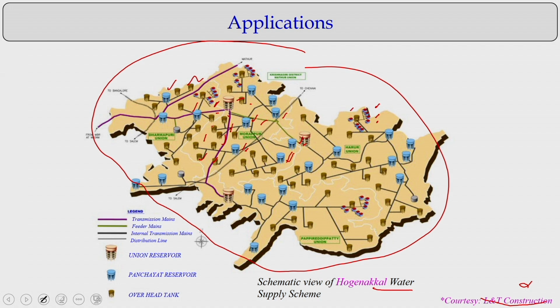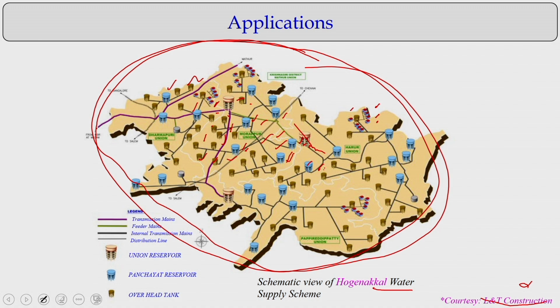If you look at a water supply system, it is like a power grid. When you plan this type of water supply system, we need to know how much loss is happening, how much pumping is required, how many overhead tanks we should design, what the network of these pipes should be, what the diameter of the pipe could be, and what type of pipe should be used. All these complex systems we design so that the total system has the least energy consumption.